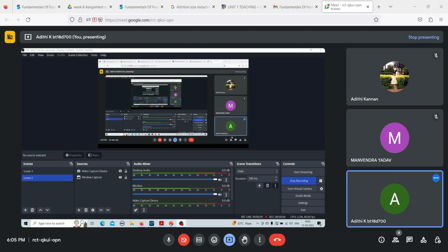We already know alpha, we know R1, the radius of the roll, and we know b. We have to calculate R2. So this is a basic substitution problem. cos 15 is equal to 0.5 plus 0.006 divided by 0.5 plus R2, which is still unknown.